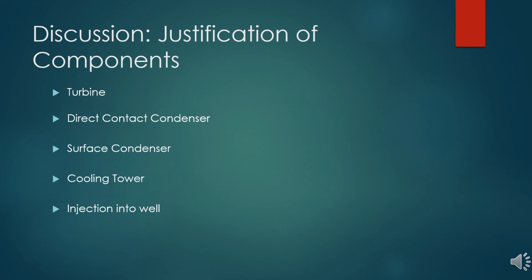The turbine inlet pressure was selected to be 6 bars. This was kept for all calculations. 6 bars was selected because this is the inlet pressure of the turbine in the geothermal power plant in Guadeloupe. Similarly, the operating pressure of the condenser was selected to match the geothermal power plant in Guadeloupe, which is 75 millibar. For the surface condenser, the operating pressure was chosen to be 90 millibar.